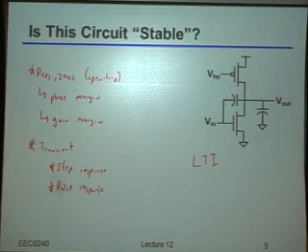And by the way, you'll actually do this, even if you're designing an oscillator that you intended to actually oscillate, you'll typically check it this same way, just with a reverse outcome, right? You'll put in a pulse and then make sure that it actually does start oscillating rather than getting stuck at a particular bias voltage. Okay? So indeed, make sure you run a few transient sims, even if you've done extensive small signal simulations, just as a final double check to really make sure that it's not going to behave strangely due to the fact that it's not really an LTI circuit. Okay?